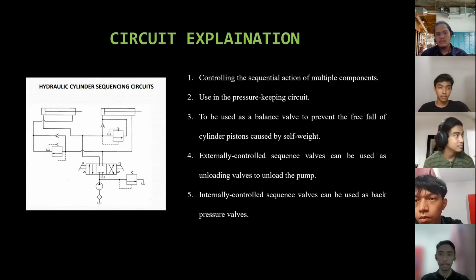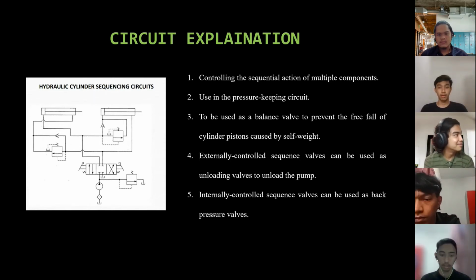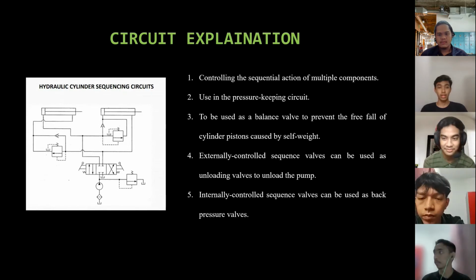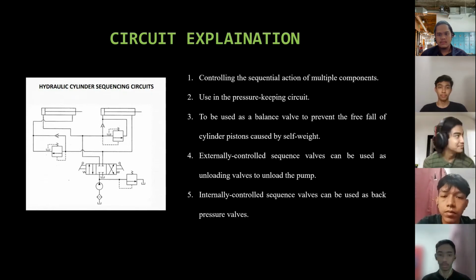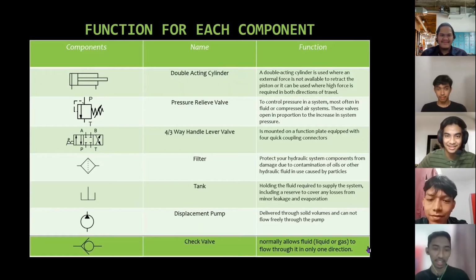A sequence valve is somewhat similar to a relief valve, except that after the set pressure has been reached, the sequence valve diverts the fluid to a second actuator or motor to do work in another part of the system. That's it. Next is the function of each component.